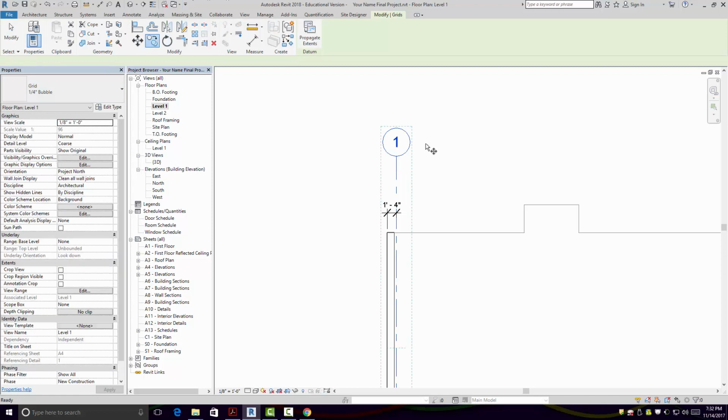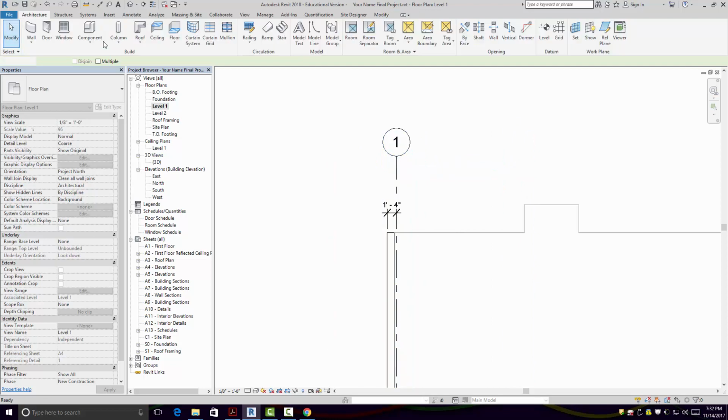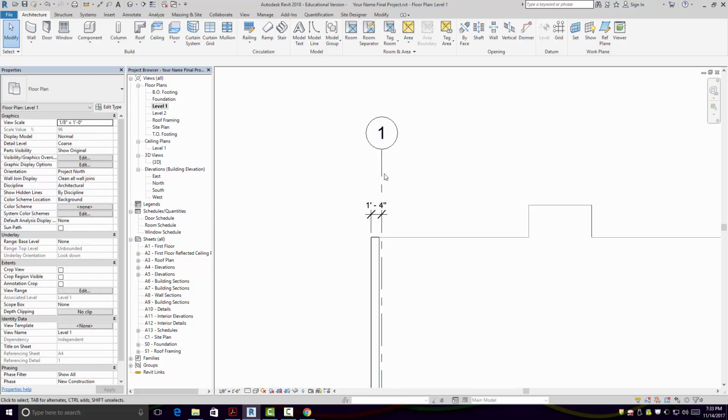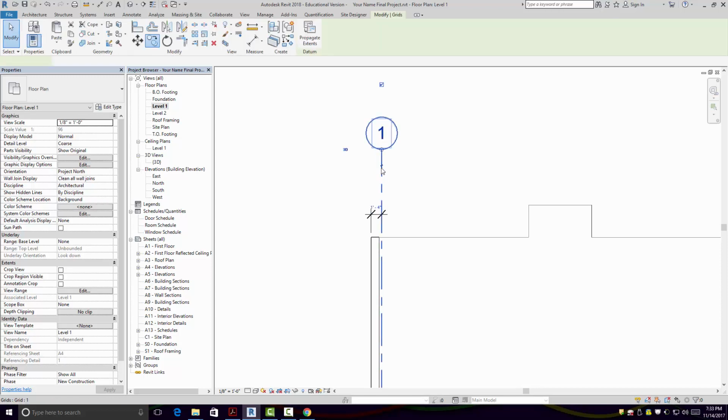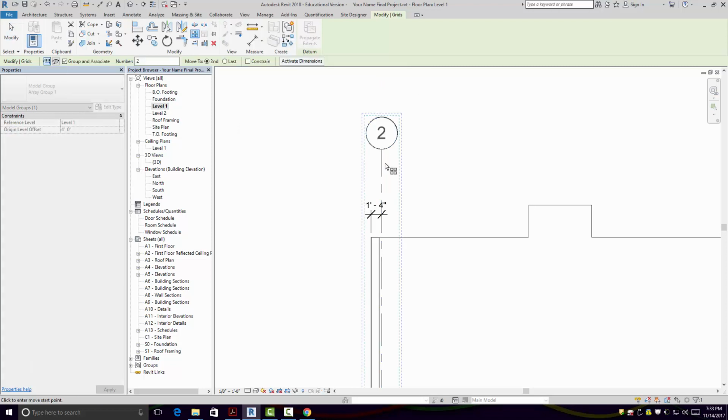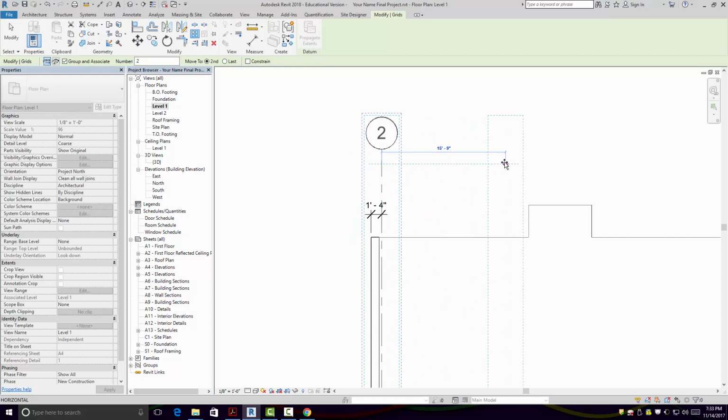But I'm going to copy the next one over 20 feet. I can array these as well. This is definitely not what I thought it was. Okay, array works this way. I'm going to array it and then ungroup it. Array is the same thing as a group, except it's a certain rhythm. So if I start with this grid and say array, that's this command right here, and I pick this and go out here 20 feet, every 20 feet it's going to pick the same item.